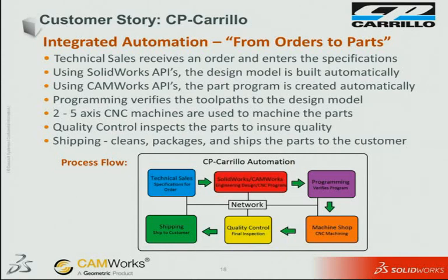So what would happen typically is that we'd take a technical sales order via telephone or even emails, and it goes into an automated system where SolidWorks captures that data automatically from our database, imports it into a SolidWorks model, generates the SolidWorks design, and then automatically incorporates CAMWorks, which is interfaced with SolidWorks, and pulls that data in and builds the CAMWorks model directly related to that SolidWorks model, all automatically.